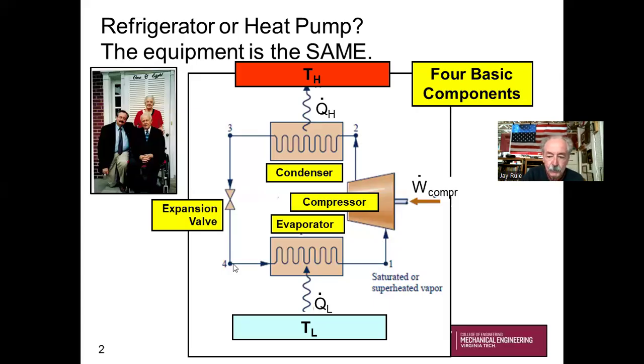That's where this refrigerant goes into the evaporator section. It's a heat exchanger is all it is, and it's absorbing heat from the cold space up in the freezer section of your refrigerator. Cold space. An evaporator is nothing more than a heat exchanger. And in high school, I had a hard time understanding what a heat exchanger was, but I got a better feel for it the more experience I got.